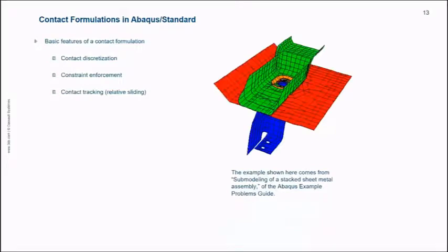All right, so that's the basics of the Abaqus standard solution method. It's not complicated in concept, but of course in practice it's very complicated to write down, say, the tangent stiffness for a large structure with contact and nonlinear material properties and all kinds of things. It's very numerically difficult to do that. Fortunately, Abaqus is programmed to do that, so we can focus on building the models.